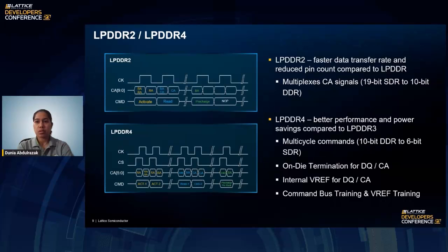LPDDR4 also supports on-die termination, internal VREF for data and command and address signals, and command bus training and VREF training, all to improve signal integrity and data integrity within the interface.